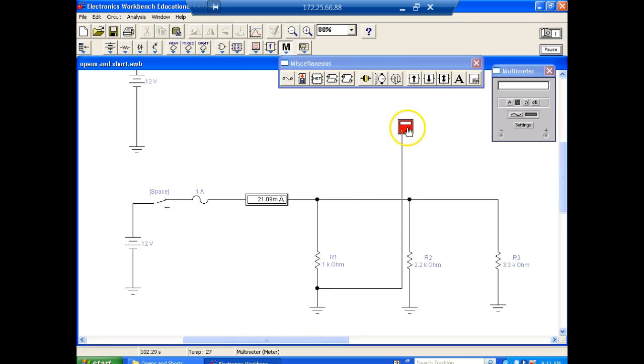So this is why you can go to any plug in your house and put your meter in that and put it on AC, and it's going to measure whatever yours measures. We say 120 volts because that's what the NEC calls the optimal voltage. But what does this measure? 12 volts. So in a parallel circuit, what's constant? Well, voltage is constant. Thank goodness. Wouldn't that be awful? In your house, if you plugged in your vacuum cleaner and now your oven couldn't work because it wasn't getting enough current, right? You understand? Because the voltage would be distributed out.